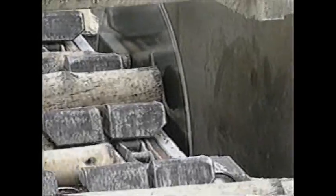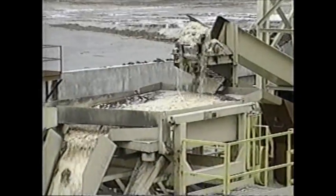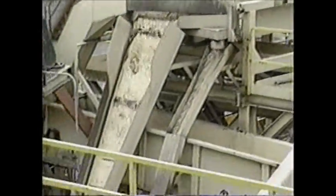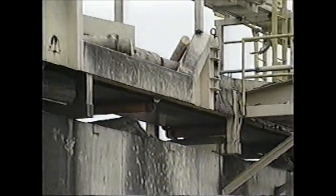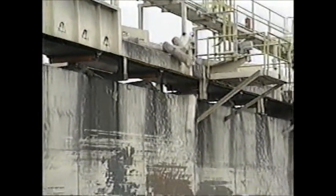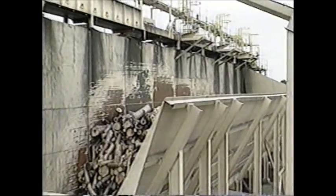After debarking, the logs are passed through a second saw, which is set for 100 inches, and are then passed through a set of saws, which cut them into 33-inch bolts. Bark and trimmings are conveyed away for boiler fuel. The processed bolts are conveyed to storage bins to be used as needed or conveyed directly into the plant for conversion into wood strands.